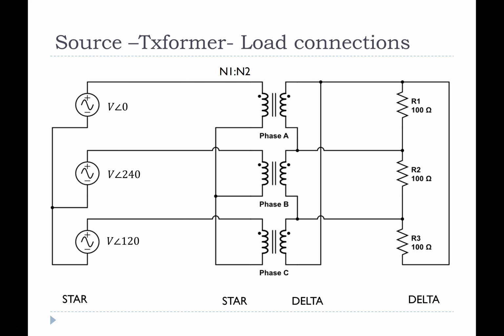So let's track the voltages here now. We have V volts, and then line to line would be √3V volts, but we want this voltage here. The voltage across the transformer winding is not the line voltage in this case. It is the line to neutral voltage.